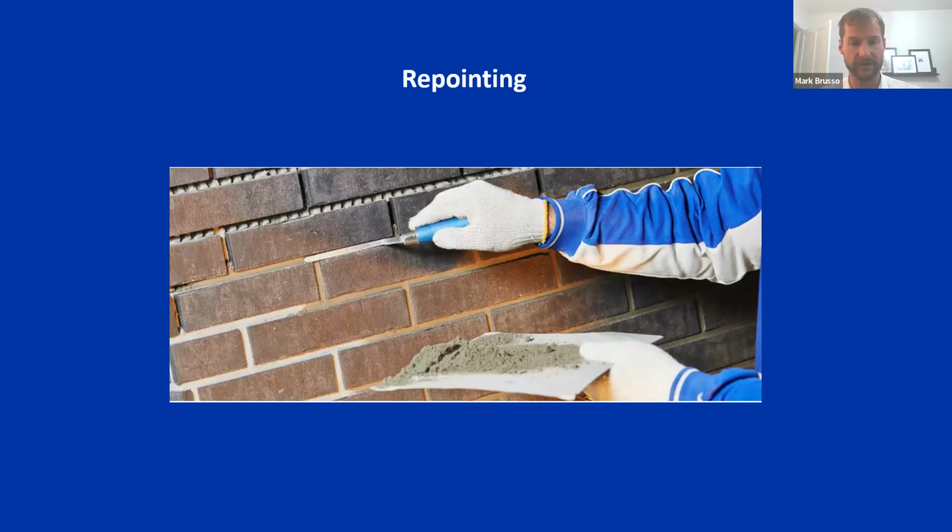Brick does an incredible job of shedding water, and in order to keep it doing that, we have to keep a close eye on the integrity of those mortar joints. Without integral mortar joints, a lot of those restoration anchors cannot perform. They rely on solid structures, solid mortar, solid brick to connect to. So they all are involved and connected closely with each other.